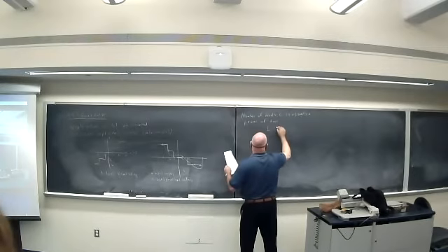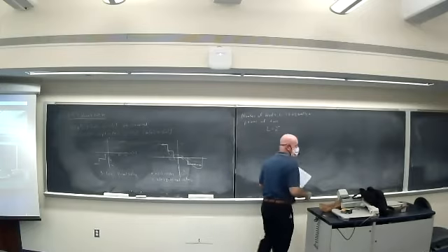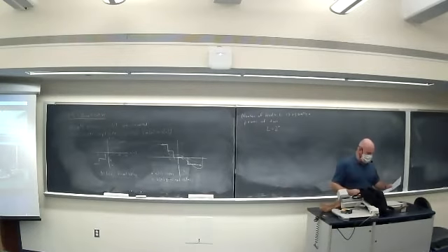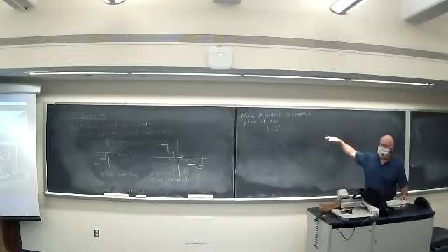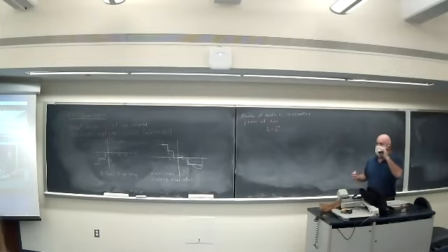So L is 2 to the n, and we almost always refer to the number of bits, and that's the n value. An 8-bit quantizer would be 256 different levels. A 12-bit is 4096. A 16-bit is 65,536 different levels in the quantizer.